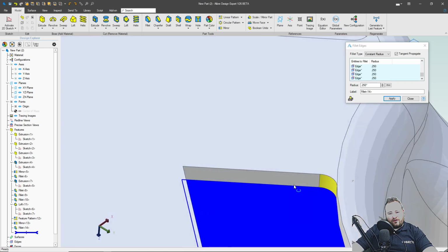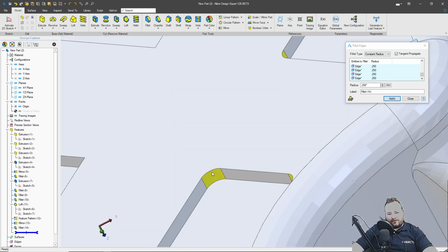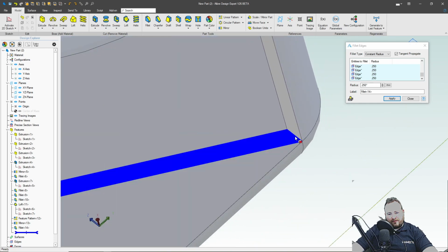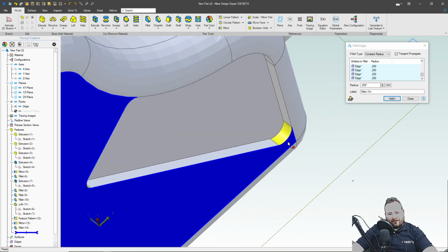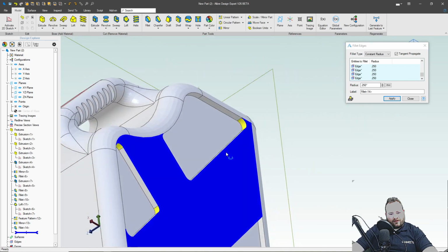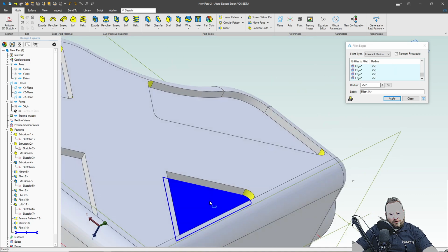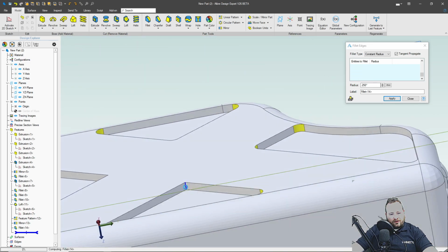And that's why it can help to not use splines and to not use lofting if you don't have to, because sometimes splines and lofting can produce very small curvatures that will make it impossible to hollow out at the thickness that you wish.